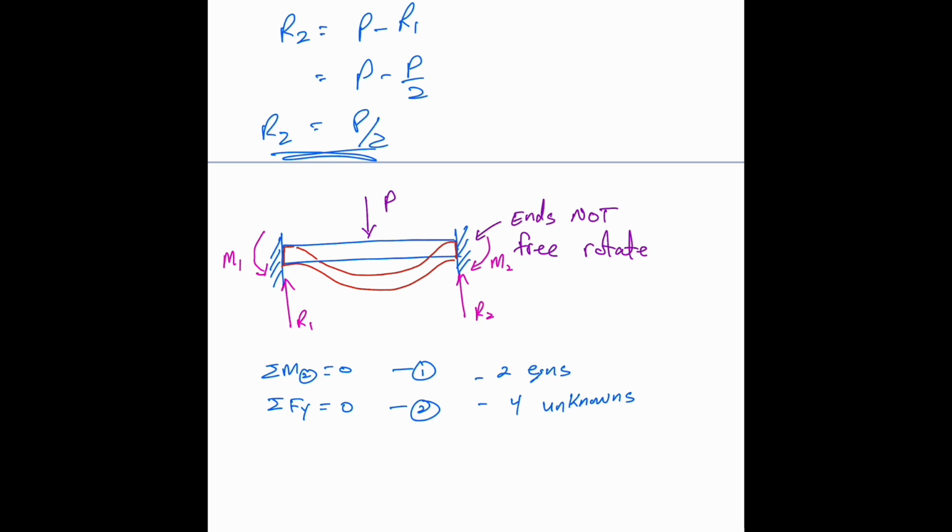Because it cannot be solved, we say we have a statically indeterminate beam, because we cannot statically determine those reactions. When we go on to year 4 and do finite element analysis, we would see how we could solve these equations. But for now, using the concept of strengths we're going to do this semester, we will not be going into any fixed-end beam, or any statically indeterminate beam.